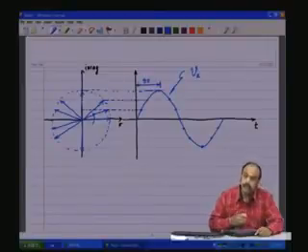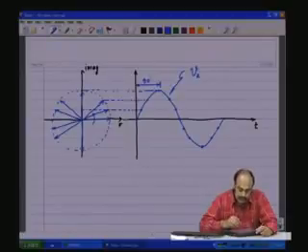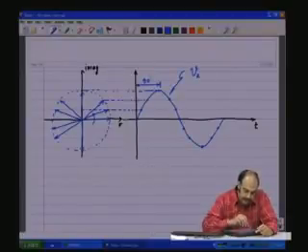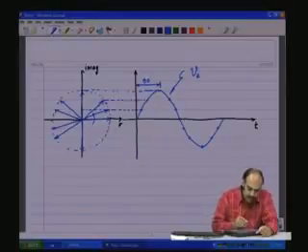And so on. So, we can say the sine wave can be considered equivalently as a phasor or a space phasor. We will call this a space phasor because it is in the complex domain and it is rotating continuously in a circle.